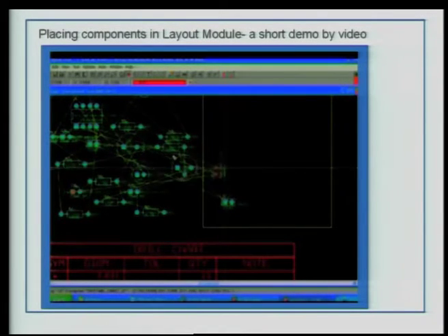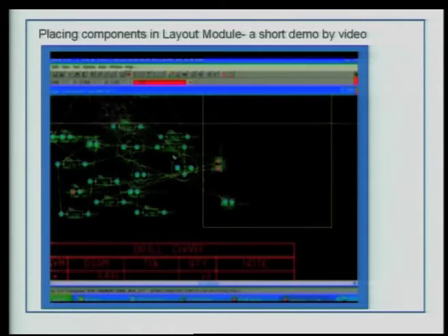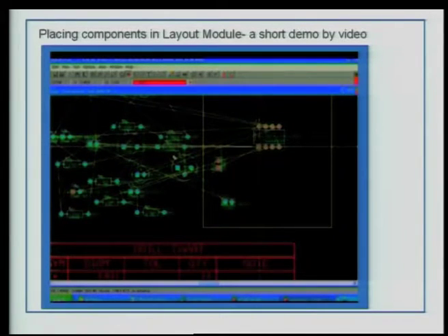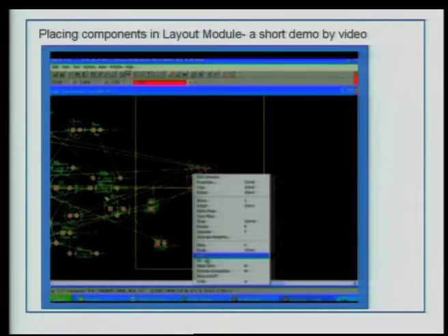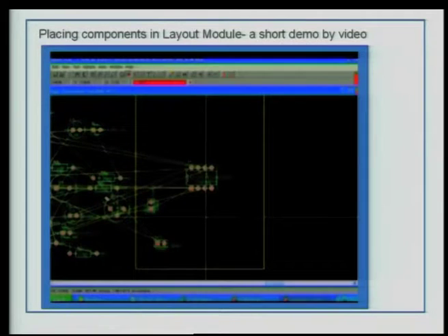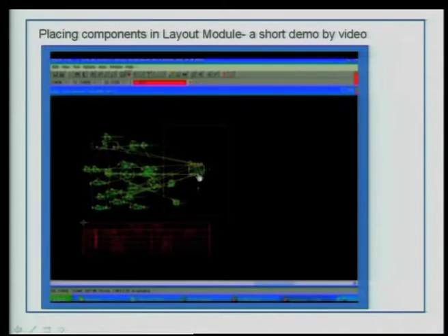So, as a designer, what I would advise you is that you should always try manual placing first, because in the case of connectors, for example, you would like to have connectors at the edges. Now, if you use a complete placement command, you may not get the placement as desired by you. For example, in this particular case, you see that the active device needs to be placed in the center of the board outline and all other passives will be built around the active device.